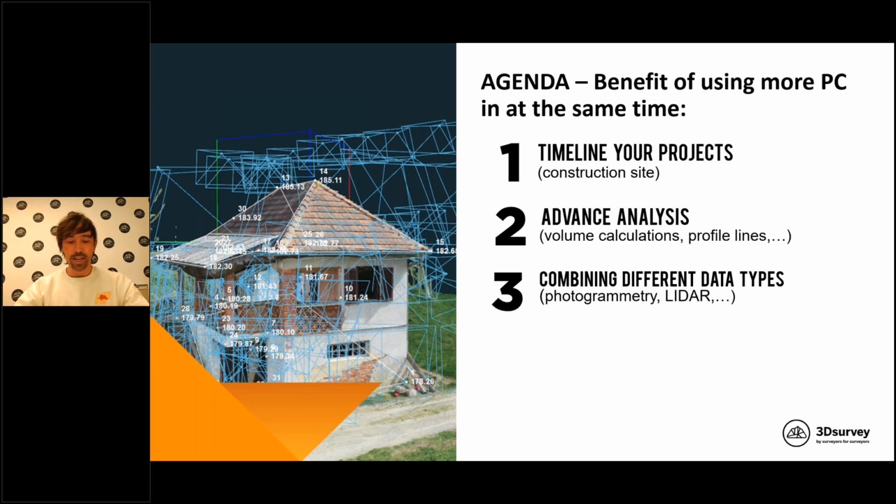The software is pretty open, which means you can load a number of different point clouds and different data types, orthophotos, textured 3D meshes or anything like that into a single project, and you can observe them, inspect them, calculate the volume differences and so on.